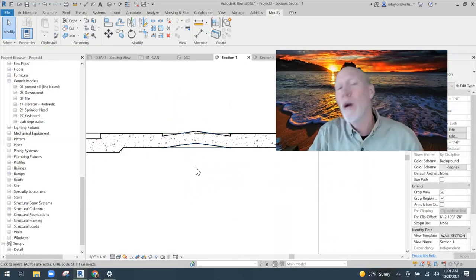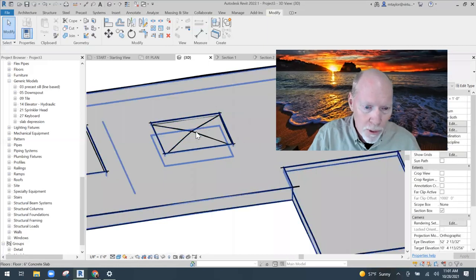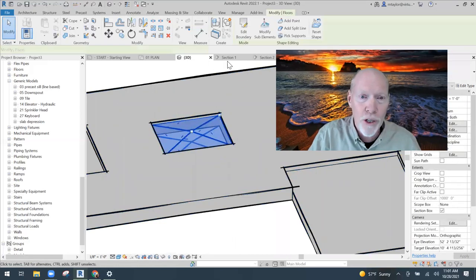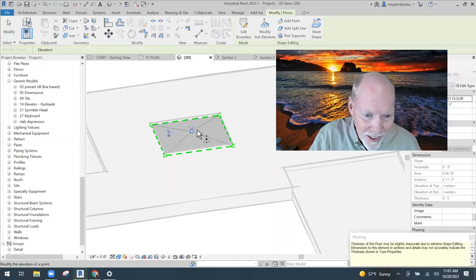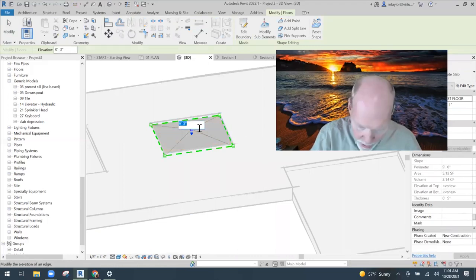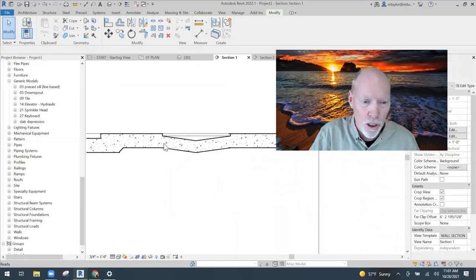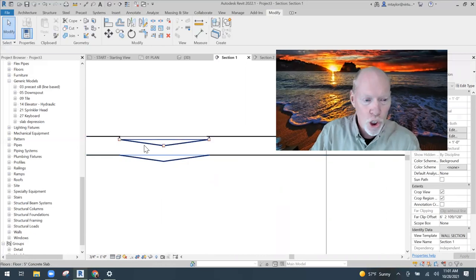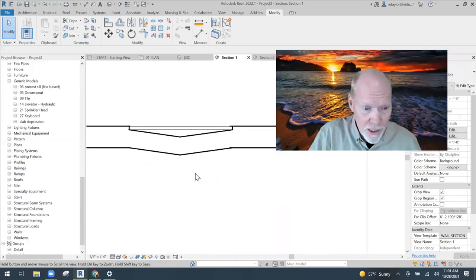Oh, well, when you modify the sub objects, you should probably tell it to go negative. Modify sub elements, pick that dot. It's not going to go up 2 inches. Oops, I want it to be -2 inches. There we go. That's more like it. So now look, this thing slopes down 2 inches. That might be a little bit drastic. And I'm gonna fix this.